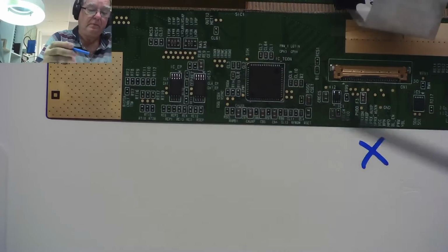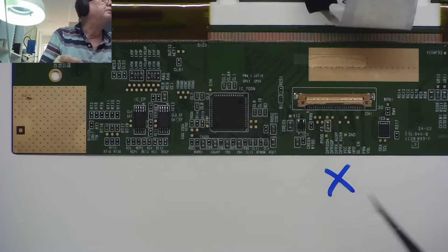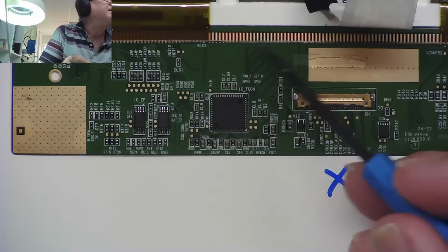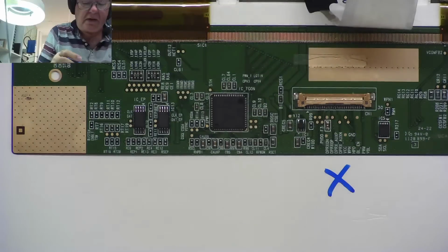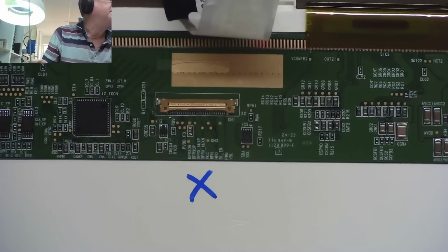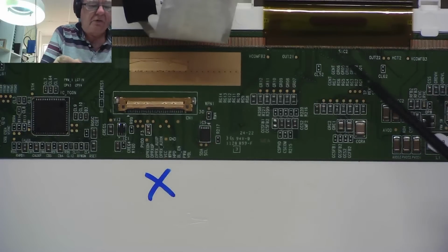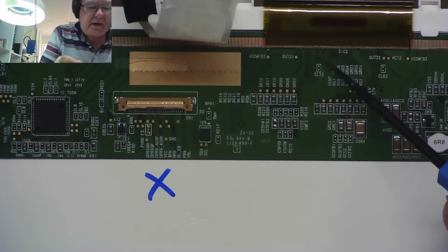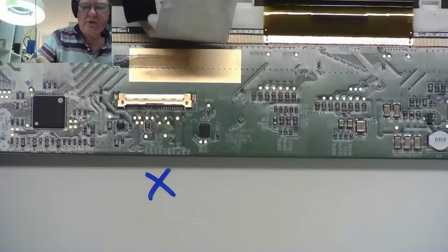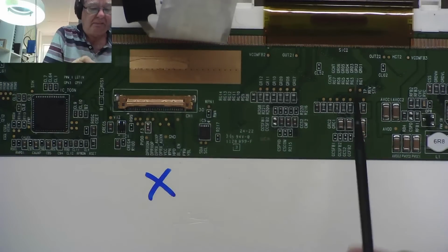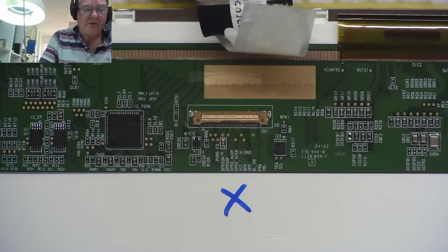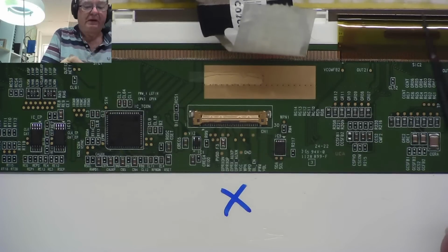If you look at the tracks coming from here, these tracks are all going from here up towards this connector here, which is powering the screen. And I'm pretty confident that there's some here as well. There's another, you can see data tracks going up here as well, and there's a load of through holes here which go to the other side. Can we turn this over? No, I'll have to disconnect the LED screen. I reckon they go on the other side of the board and all back to here. So I'm sure this is what's driving these ribbons. Then we have the chip on flex, which we mentioned actually on the ribbon itself.